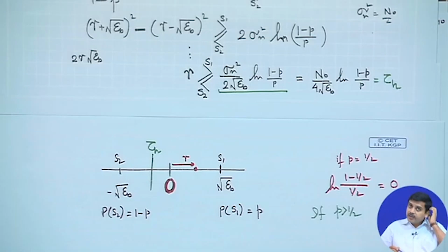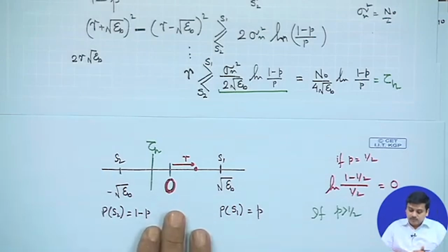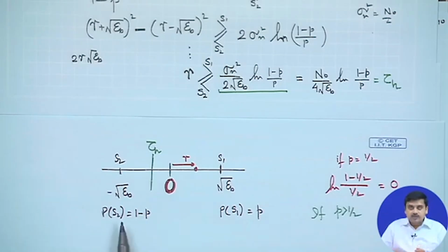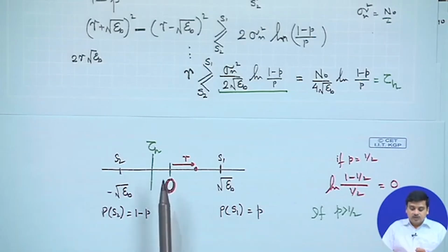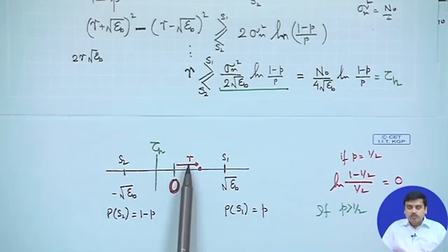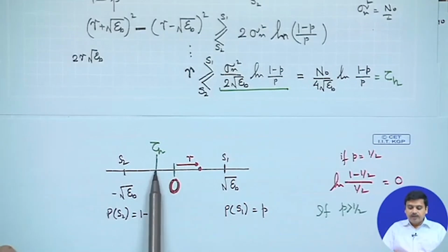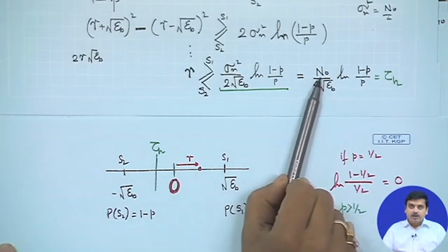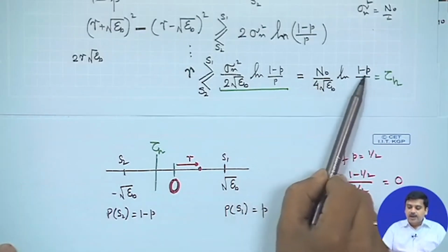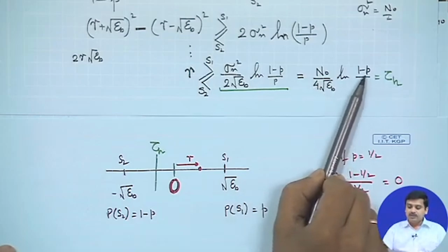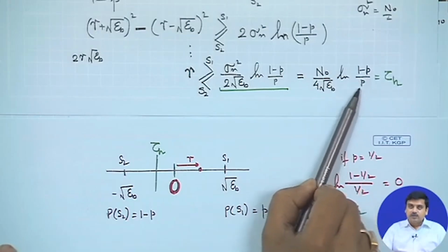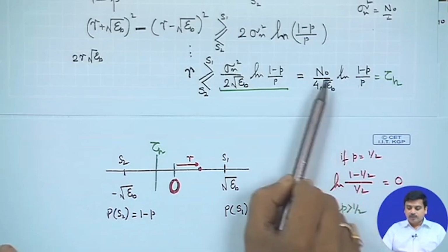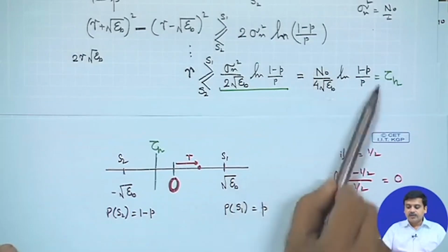So, now we can see that if in this case we know the prior probabilities, then the way we implement our receiver would be, you simply get the output of the matched filter, compare it with a threshold which requires the knowledge of N naught, E_b and P. P is the probability of transmitting a particular constellation. It requires N naught and E_b, because accordingly things get scaled.